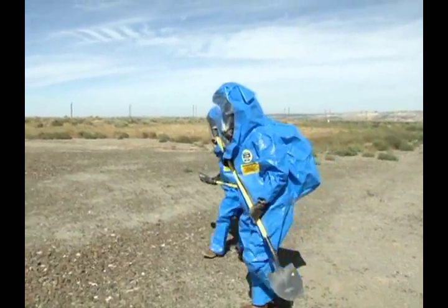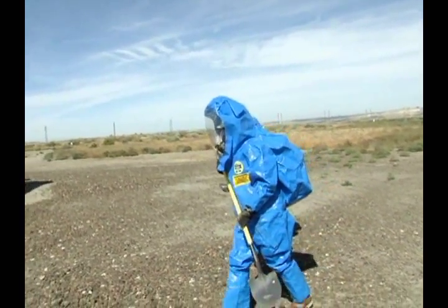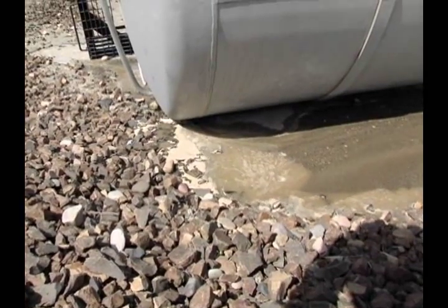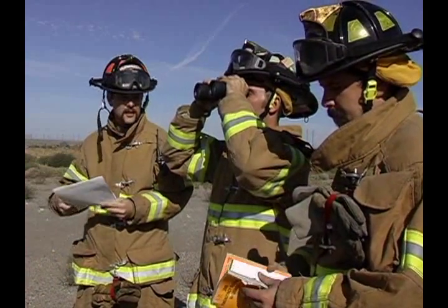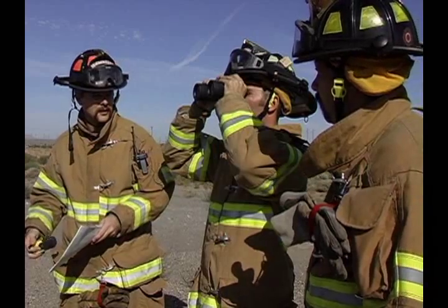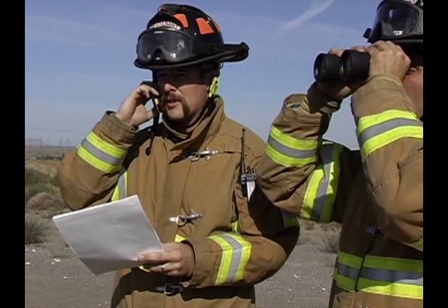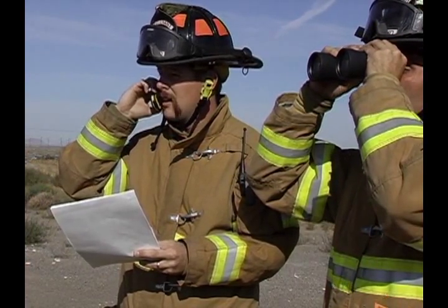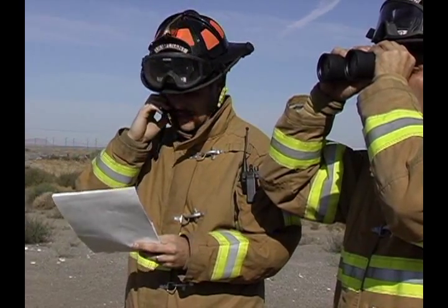When you are working out of doors, you also need to account for physical hazards. In an incident where retention holes need to be dug, hazards from utilities and underground pipes should be recognized before digging. Initiate a one-call to local utilities to find out if you're going to compound the hazards on scene.